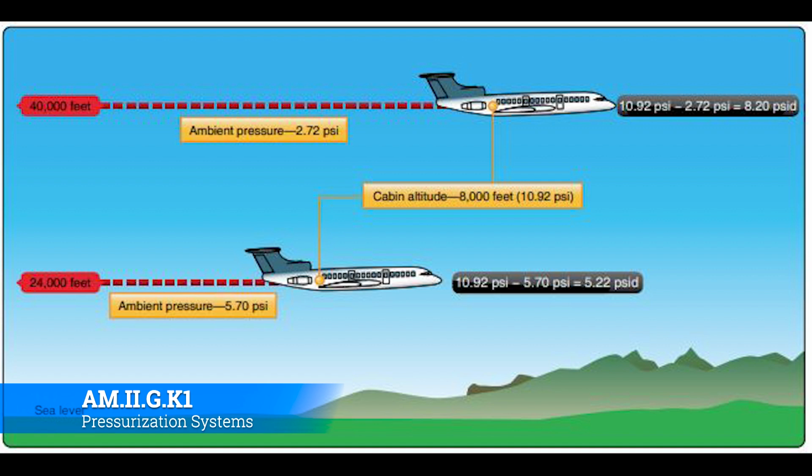So if you go 100 feet a minute, that's really, really slow, and basically no one will ever feel the difference. But if you go 10,000 feet a minute, so in one minute it goes from being one pressure to something totally different, that's when you're going to get a bunch of people popping their ears and complaining to the stewardesses. So it's real important to maintain a good steady rate, probably under 500 feet a minute, because that's kind of your standard rate to keep people comfortable. So that's the basic vocabulary when it comes to pressurization. You have differential pressure, rate of climb, and then cabin altitude.